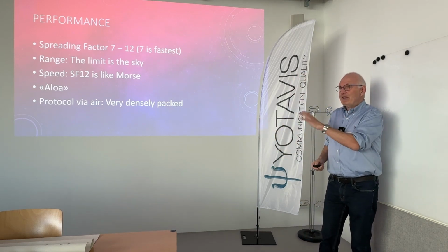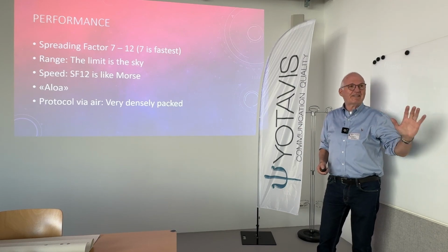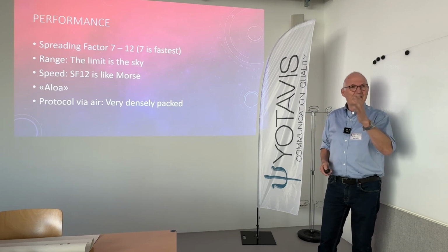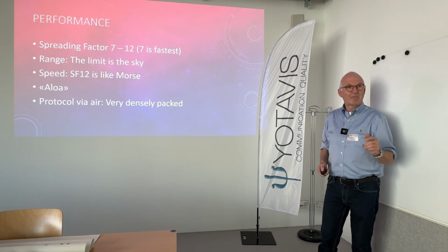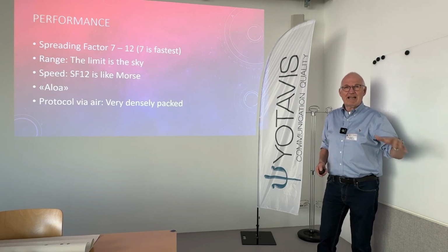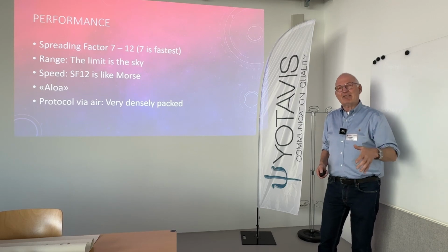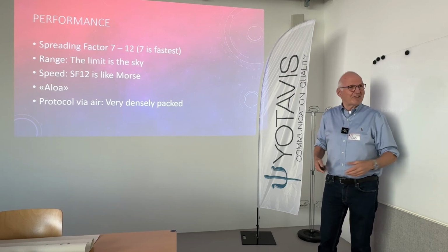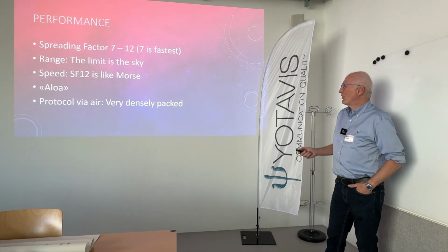And for all these ISM bands, there is one thing: duty cycle is less than 1%. So your sensor must not transmit more than 1% of the time. Don't ask me how it is calculated. I calculate it every day. Others say every hour, but every day is better for me because when I switch off the sensor, then I usually achieve it in 24 hours.